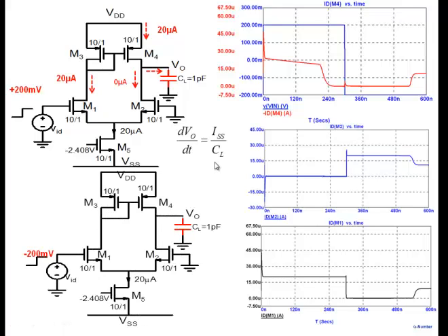Alright, something very interesting occurs when you go to negative. Now, negative, what did we say in negative? We said that current switching will not occur. If current switching doesn't occur, then how will the capacitance discharge? Let's say this is 20, this is 10, this is 10, this is 10. Then how will the capacitance ever discharge? So now keep in mind that this voltage initially is 3.3. It is a positive swing. Positive is charged to 3.3 here.